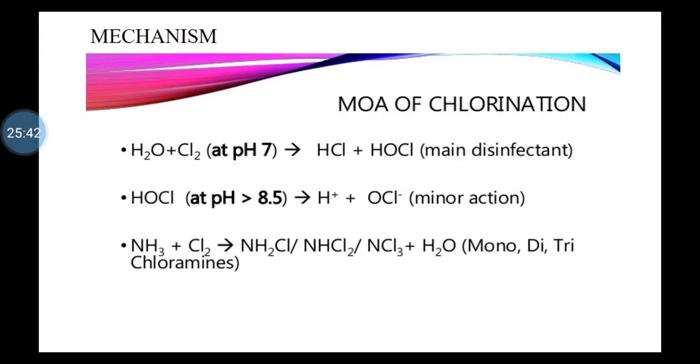This is mechanism of action, that exactly when water is mixed with chlorine compound, what action takes place? Now the chemical action of chlorine with water is due to formation of hypochlorous acid. So in first reaction you will see that there is formation of hypochlorous acid, that is HOCl. HOCl is hypochlorous acid. And hypochlorite, that is in the second reaction, that is OCl.